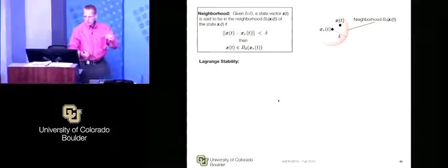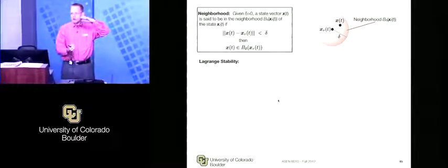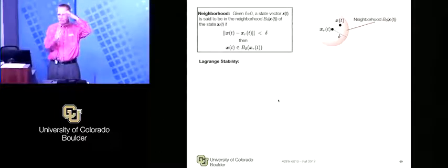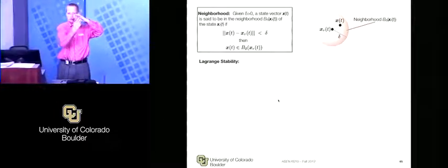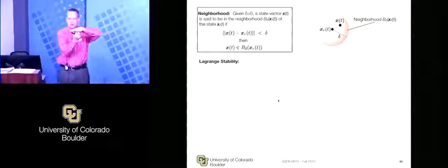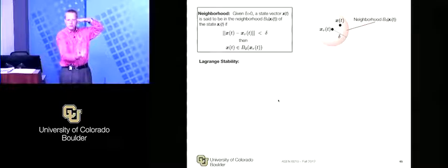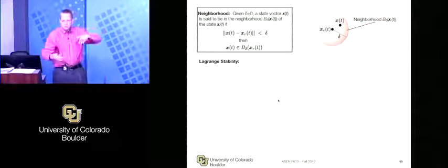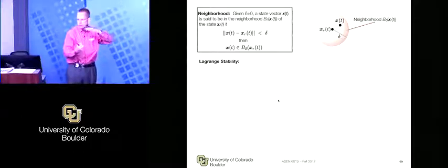It's boundedness. Think of a spring mass damper system. If you just have a spring mass damper floating in space, things will settle and the spring settles to the origin, right? If you put this system now in a gravity field, we will settle but never at the origin. It always settles at an offset, right? Where the spring force balances the gravitational force, essentially.